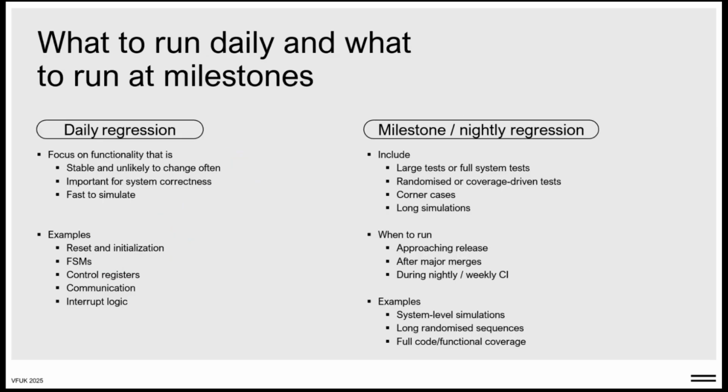So now that we have a good strategy, we need to know how to use it. Daily regression should focus on fast, stable, and critical functionality, like resets, FSMs, registers, and protocols, while milestones or nightly runs can include full system tests, corner cases, and long simulations.